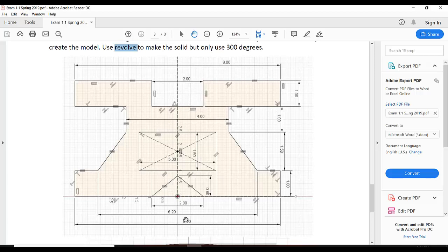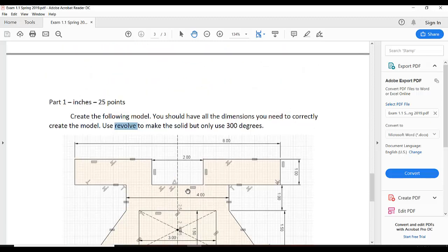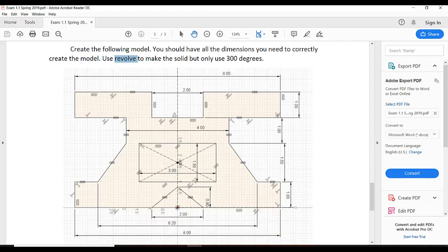To make a half sketch like this, the total dimension is 8, from this point to this point, with the origin in the middle. So to add the half sketch, we are going to add a dimension of 4 inches from this point to this origin. You will closely observe in the video which dimensions I am going to make half.